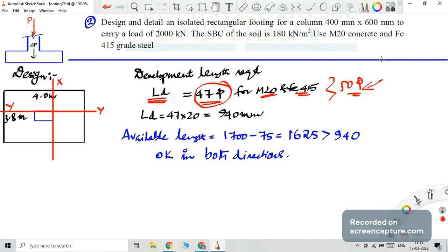Suppose you get a 12 meter reinforcement, then one length can be 12 meter. Then to make it into 20 meter, you have a shortage of 8 meters. So don't use 12 plus 8, but you need 12 plus 8 point something.